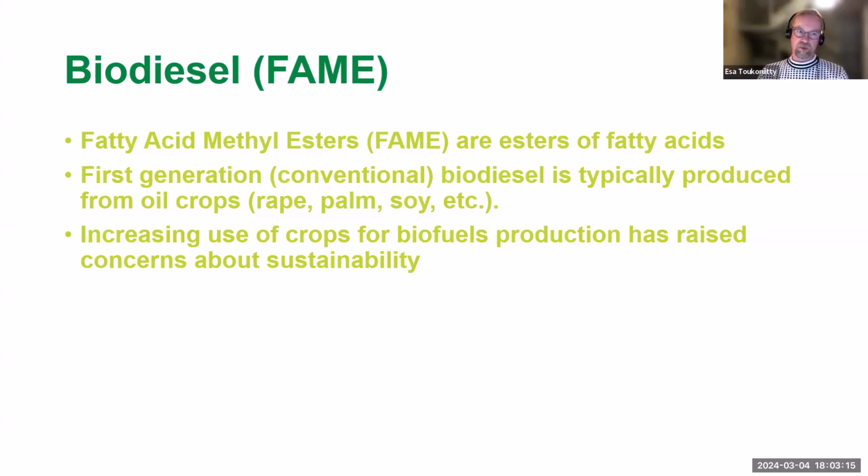So it's quite simple to make. You mix just alcohol and the fats or lipids and add some base or acid, and then you end up with this product, the FAME, fatty acid methyl ester, and it can be used in diesel engines.